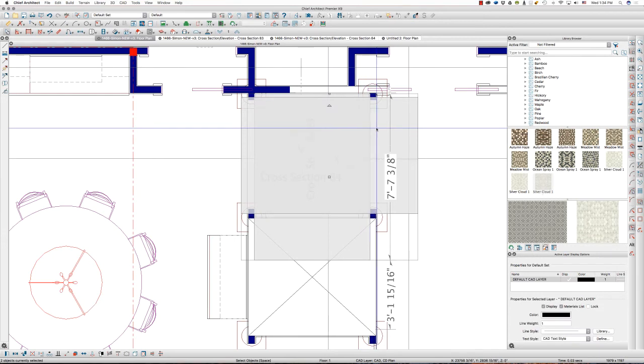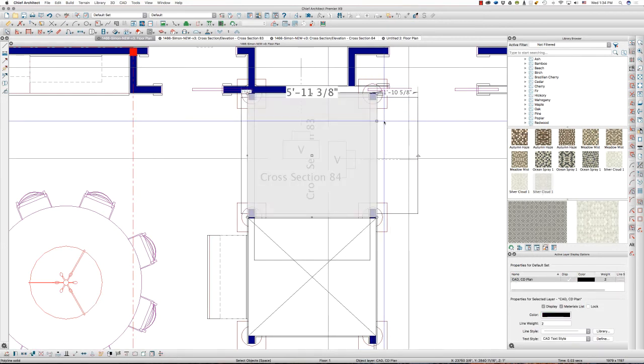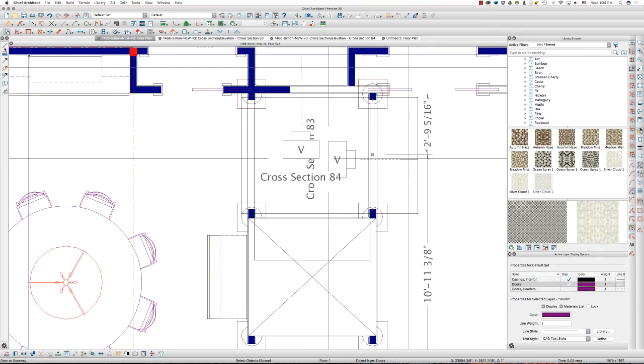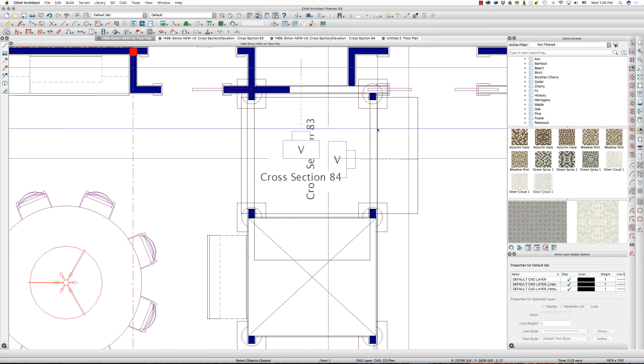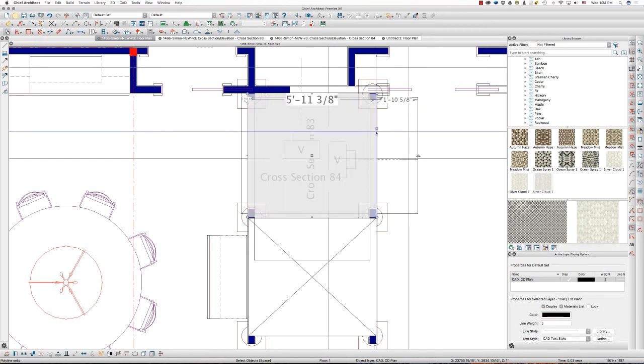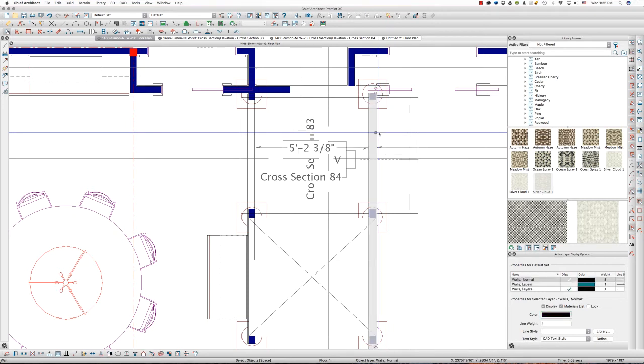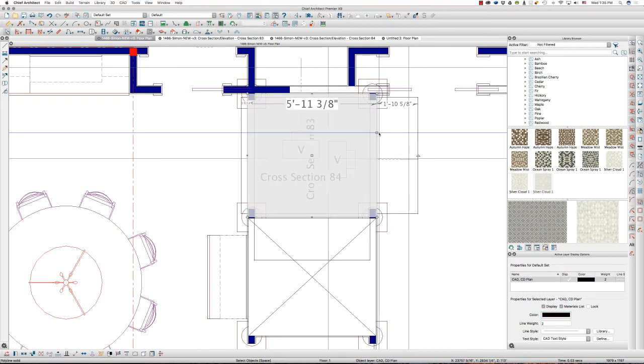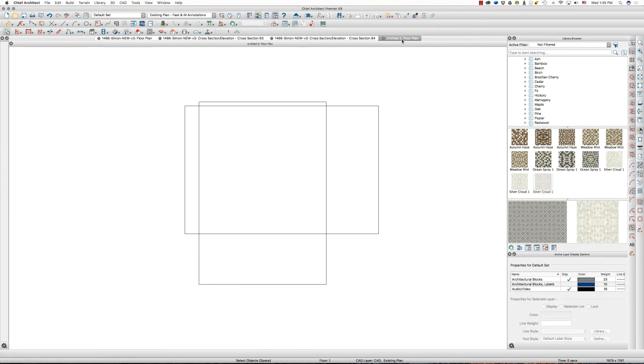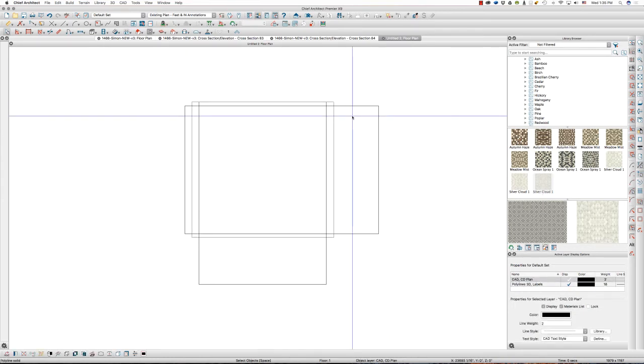The last thing I need is this square one that I created, and that's right there. So I'm in my select objects mode, the space bar or the arrow up there on the left, and as I click, say I selected the doorway first, I'm going to tab, that selects the wall, tab one more time, and there's my polyline solid. So I'm going to Command C, go to my new floor plan, and Command Option V for paste hold in place. All right.